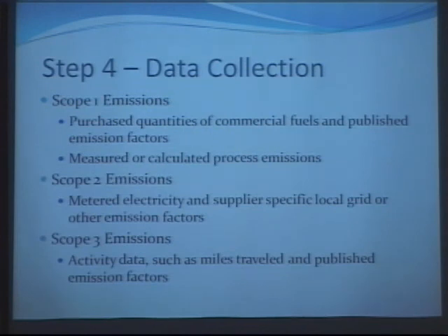So once you decide your sources and your boundaries and your emission factors, then you start looking for your data. And again, you're looking for your purchased quantities of commercial fuels, and then you assemble the appropriate published emission factors to go with the types of fuels that you're using. You look at your metered electricity. When you are trying to calculate the emissions associated with electricity,